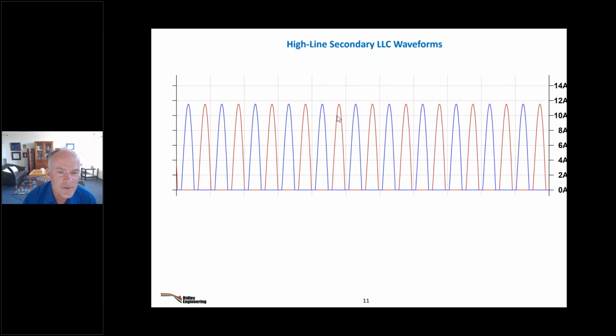Range of voltage would use half wave versus full wave. It's a device question. Which field are you in? How much over voltage do you have to have on your devices? Everybody's got a different choice there. There are some serious advantages to full wave in that you clamp the voltages better on the devices, so it can be nice to do that even at fairly low voltages. There's no canned answer to that.